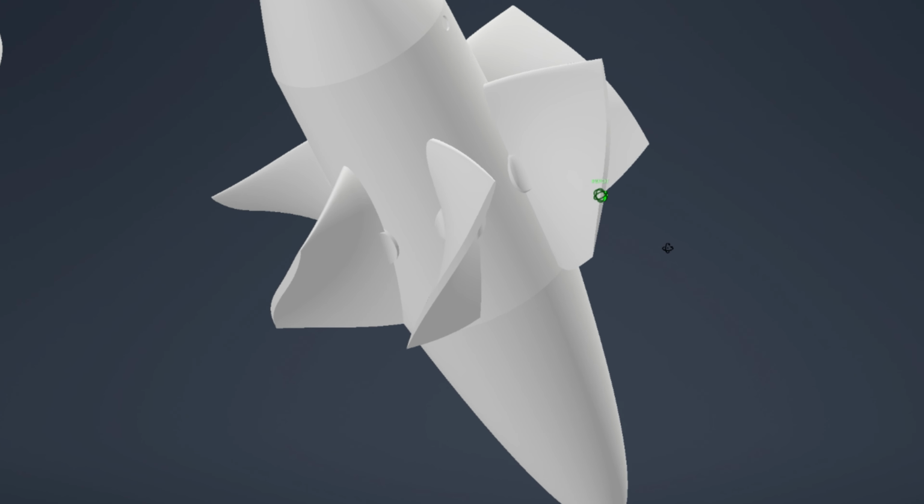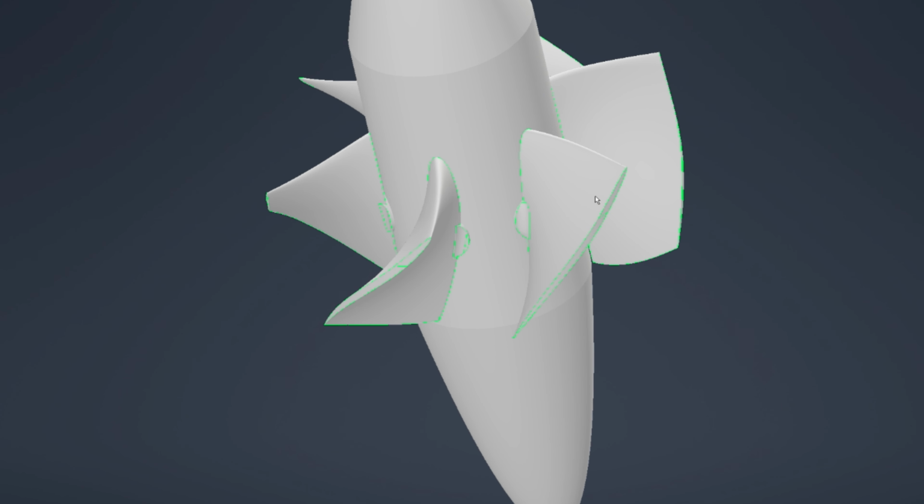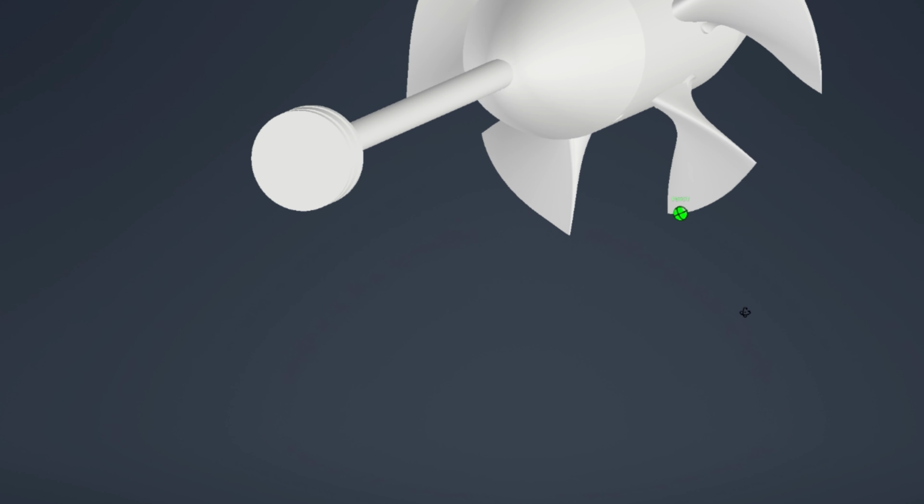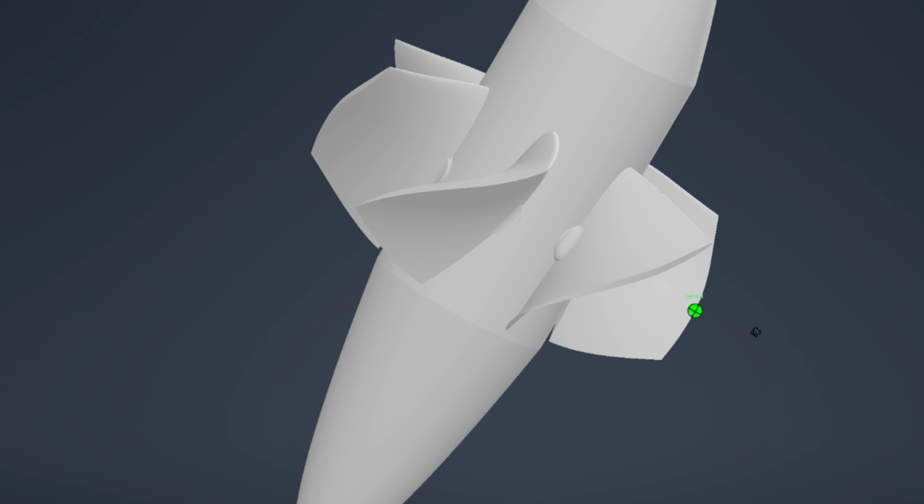Last piece on the runner, and this is the one that gets its name, the Kaplan. Almost every Kaplan has a variable pitch blade in the hub, and this is extremely important, because Kaplans are highly sensitive to the angle of attack. This, in our application, does two jobs at once.